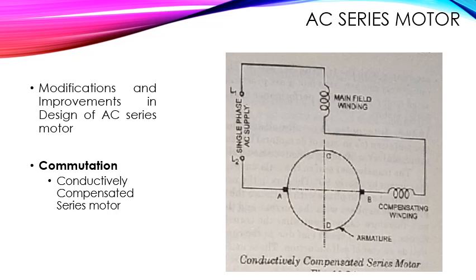The next one is, to obtain sufficient flux with fewer ampere turns per pole, the reluctance of the magnetic circuit must be reduced to a minimum. This is achieved by operating the iron at low flux density and therefore at high permeability, and by using a very short air gap. And because of the small number of field ampere turns and very low flux density, a short pole is required.